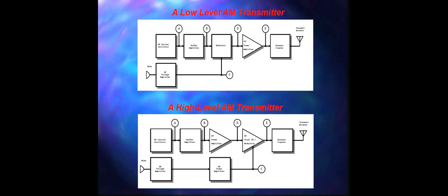Then we need to transform the antenna impedance from 50 ohms down to around 25 ohms. So here special transformers can be used to match the impedance, and along with that we can also use LC resonant circuits.